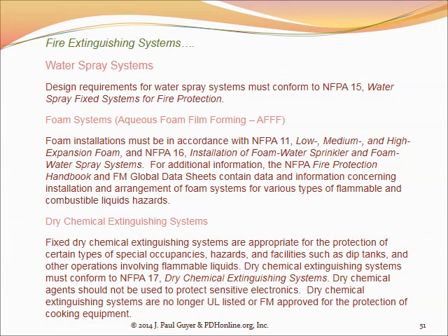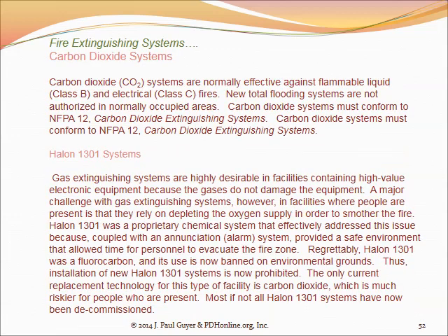Carbon dioxide is another good extinguishing agent. It extinguishes the fire by smothering it, by depriving it of oxygen. Carbon dioxide could be used on grease fires, could be used on electrical fires, this sort of thing. The problem with carbon dioxide, though, is that by denying the fire oxygen in the atmosphere, it's also denying the building occupants oxygen, and so they are put at risk. And so carbon dioxide systems are used only in areas that are not normally occupied by humans, like a transformer vault or something like that.